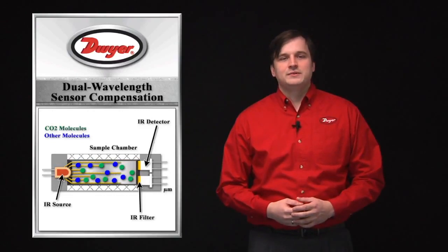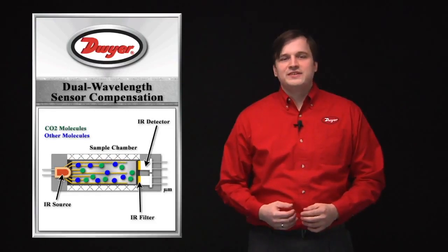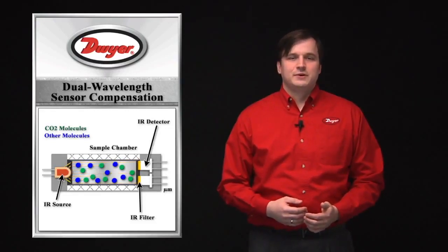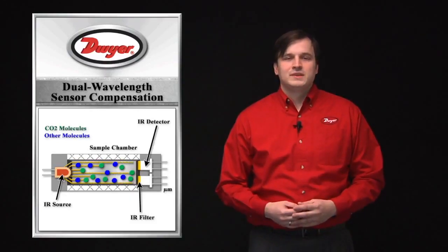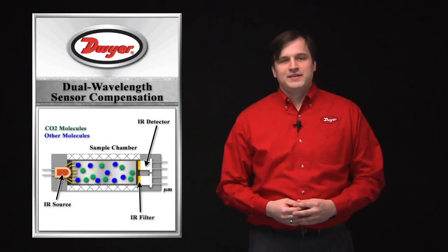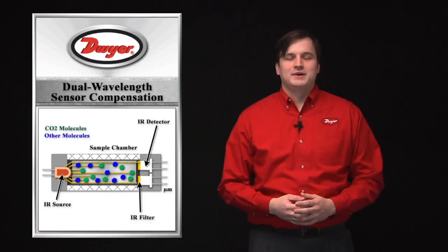Over time, the light source used in NDIR CO2 sensors dims, creating drift in the sensor readings. With other sensing technologies, this is corrected for using algorithms that automatically self-calibrate the device. Unwanted errors can be induced by this self-calibration procedure, especially in cases where the space may be occupied 24 hours a day.